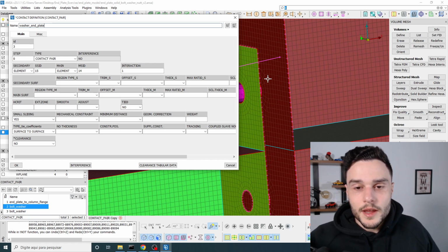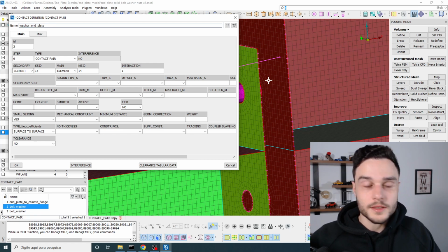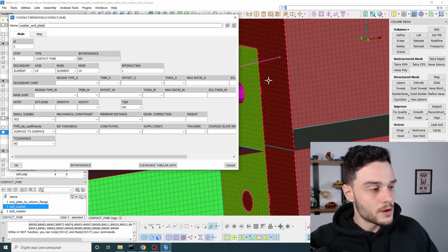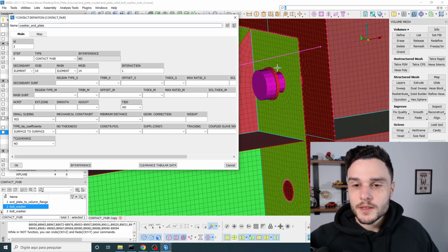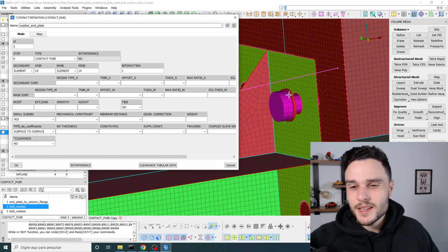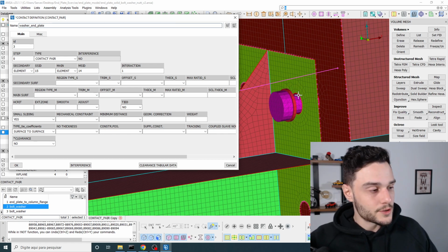This is just something that I got from Abaqus manual or user's guide. But in the user's guide, we have this information in different places. So in here, I put it in only one place. So there is one thing here that is about stiffness of these structures. In this case, we have a plate, and it's not a thin plate. And we have the contact between the washer and plate. In this case, the thickness, the stiffness is not going to be so much different, actually.